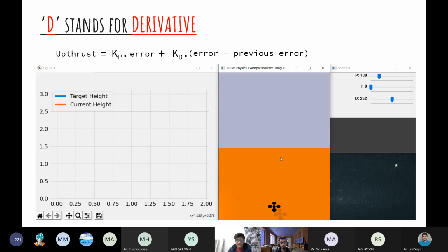Wow, it has really stopped our drone at the desired height. But what is now going on here? Why has our drone achieved a steady state at a lower height? In this particular case, we can have an external factor that is imposing an unwanted force on the drone. If you guessed gravity, then you are correct. So we can argue that adding a constant term might resolve the problem.